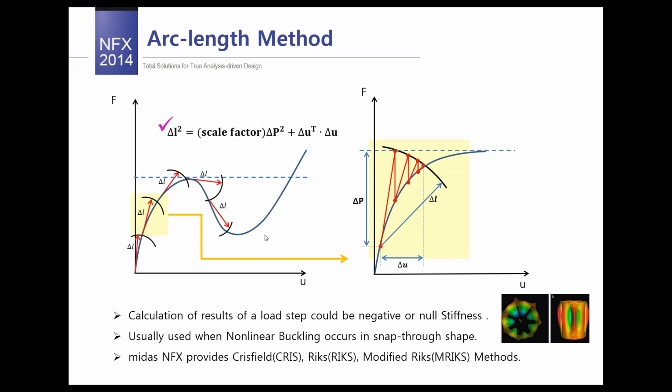The same at this point, for example. So standard solution techniques lead to instability near the limit points, and it's not possible to catch the right solution for snap-through and snap-back points, and many of the problems simply fail.